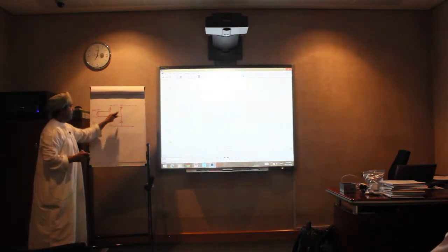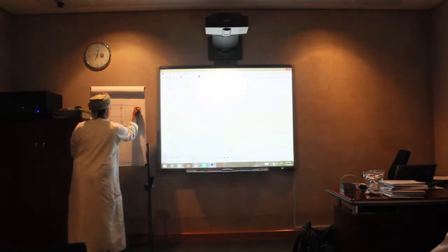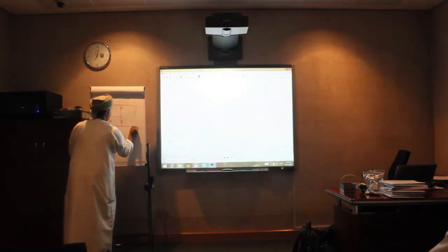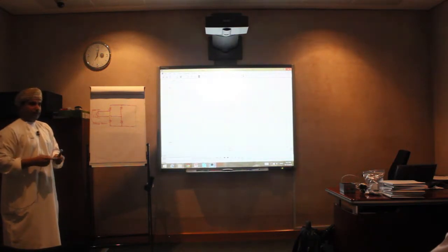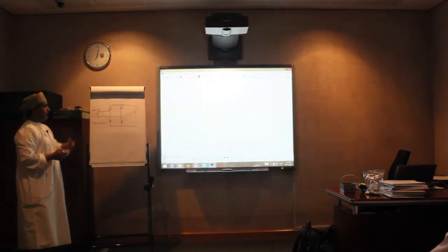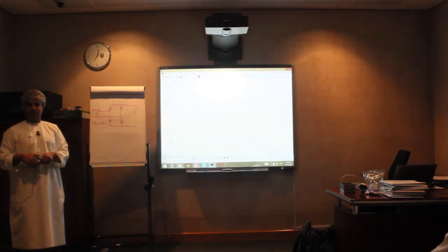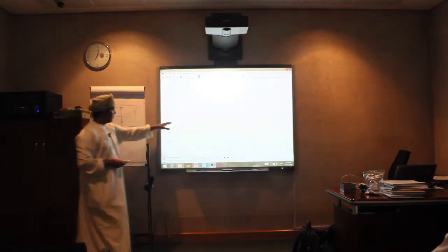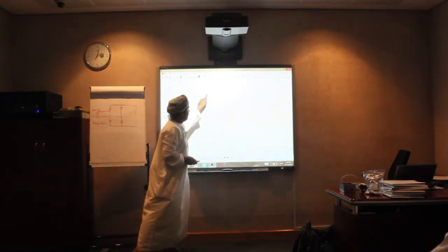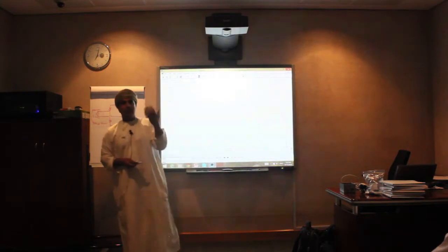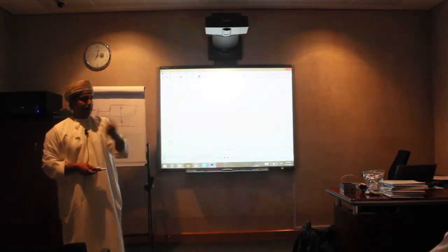And then 4 diodes, and then connect this one to a load, a resistor for the first one. Okay. So let's look at that one. The same thing we can analyze like before, but now we will gain that this part will be inverted to the other side. That means we will utilize the whole wave instead of just the half wave.